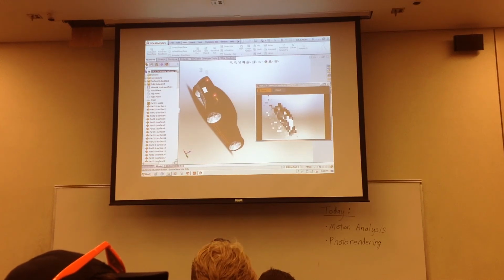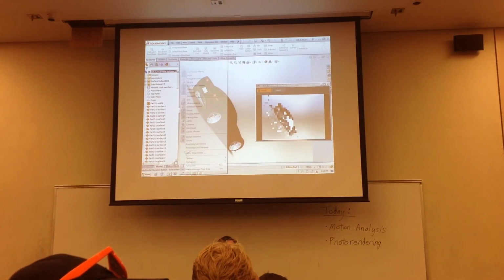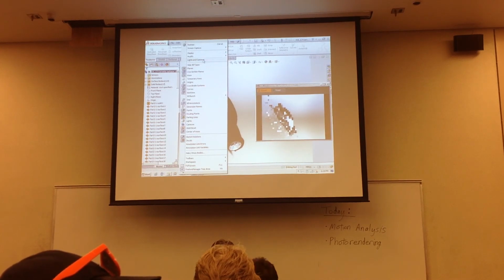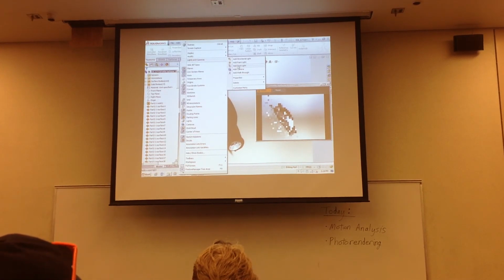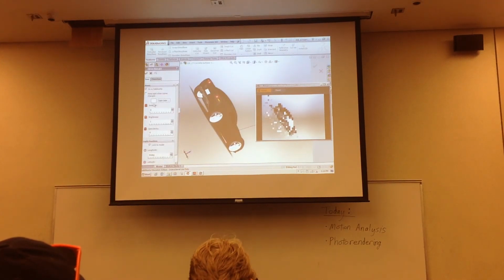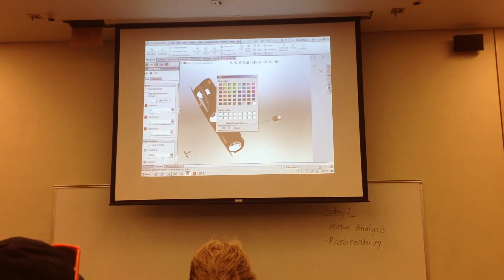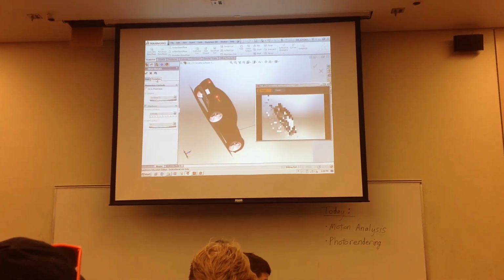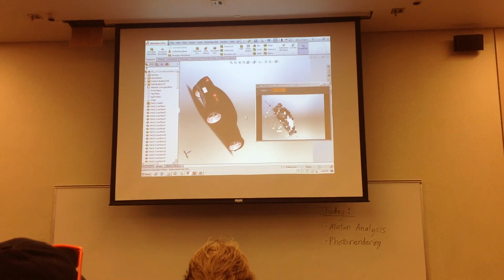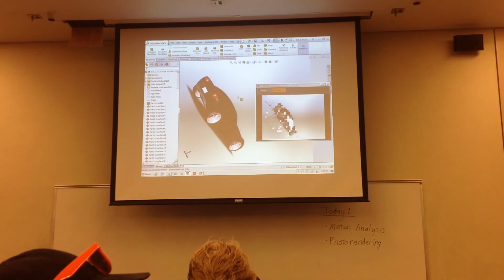You can drag it around just like I did the camera to put it in different positions. Okay, so lights and cameras: add spotlight or add directional light. You can change its color to make it red. You can drag it around here to adjust where it is. You can choose whether or not it's going to have an effect on the photo view, so make sure you check that box. Say okay, otherwise it won't show up in your image. But now you can see the red tint to the wheels. That's the effect of the spotlight that I just added.